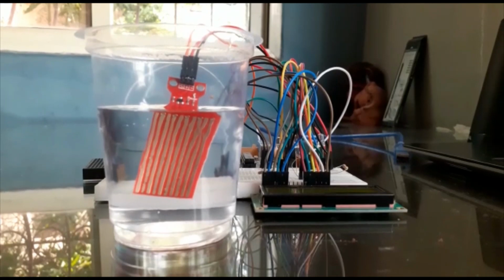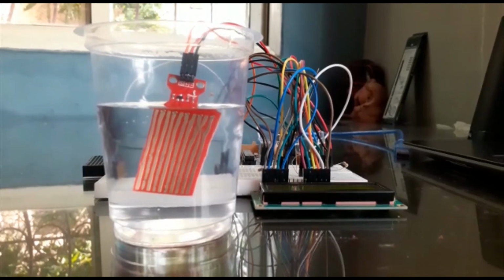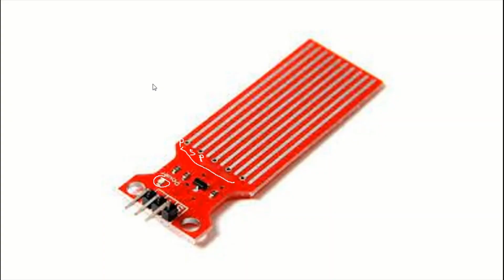We have already learned LED and LCD in detail. So today, let me introduce you to the water level detection sensor and a passive buzzer. This is how a water level detection sensor looks. It consists of a series of 10 exposed copper traces, 5 of which are power traces and 5 of which are sense traces. One sense trace, indicated by S, between two power traces, indicated by P, are bridged by water, thus connecting the traces and completing the circuit.